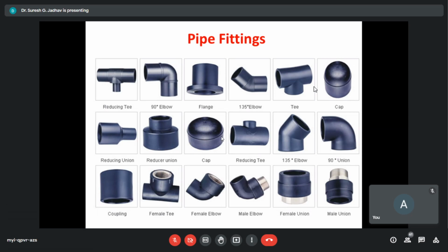Now the next component is a bushing. So we use a bush for connecting pipes of different sizes. The male end is into the coupling, and the smaller pipe is then screwed into the female end. The smaller connection may be tapped eccentrically to permit free drainage of water with the help of bushing. So with the help of bushing, we can connect pipes of different sizes.